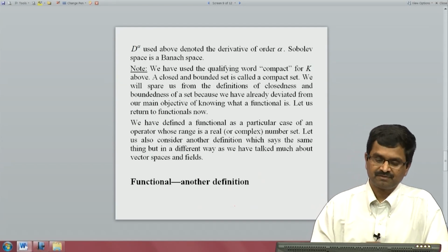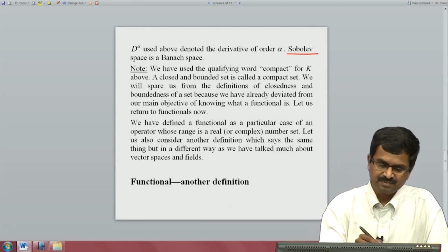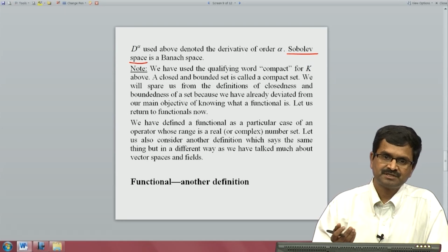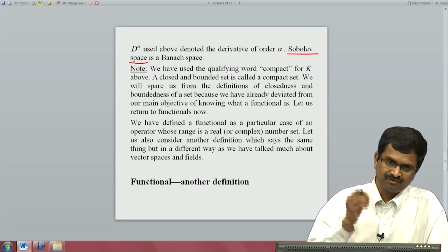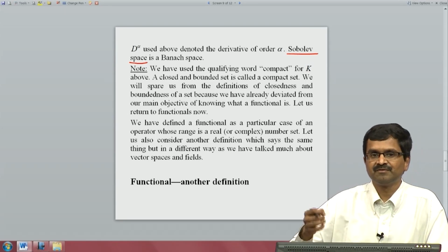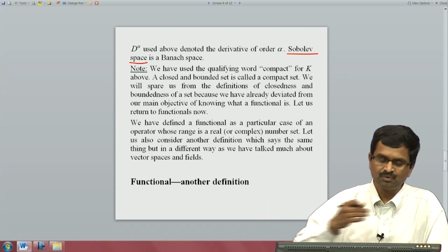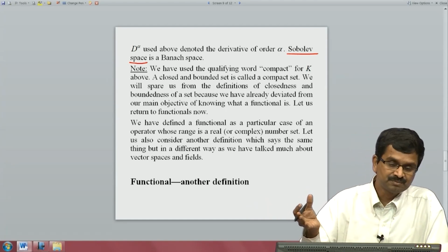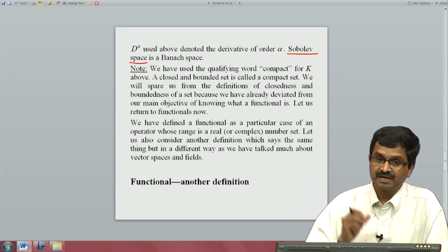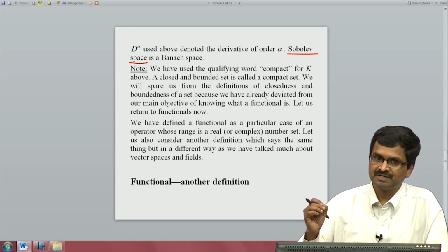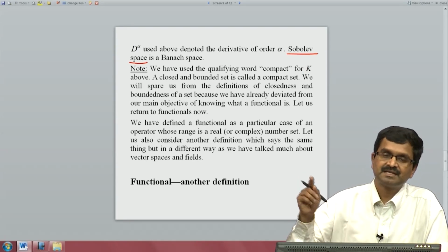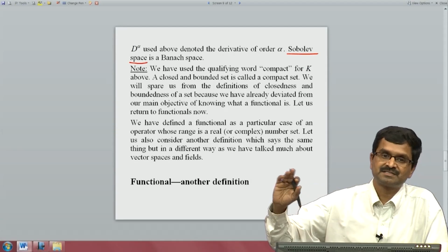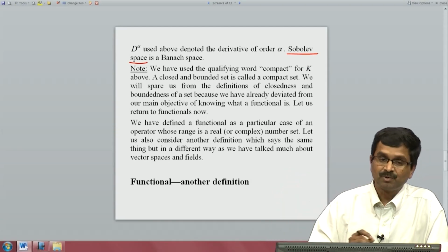The Sobolev space that we talk about is an energy space, because most of the strain energy and potential energy contain the function, its first derivative, second derivative and so forth. Normally in mechanics you do not go beyond the second derivative, but you can in principle. There are energy spaces where those energies are finite, because if you see the Lebesgue norm, we said that should be less than infinity. You cannot have infinite strain energy. That is why Sobolev spaces are important.